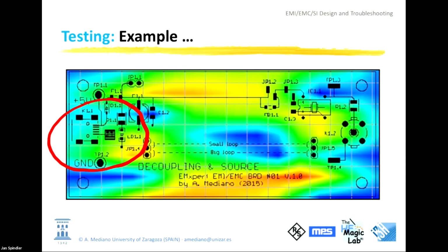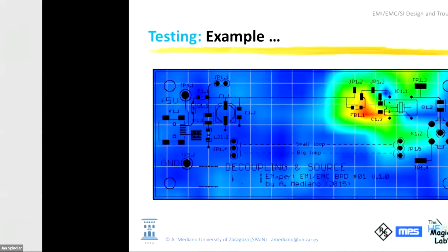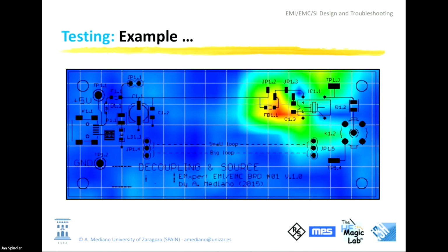The important thing is, when you introduce the decoupling system, what happens? How do you think that this will change with the decoupling circuit? Where will the energy be? Instead of around the PCB, creating crosstalk, creating radiation, creating common mode impedance in sensitive traces in this ground system, the energy will be around the element that is the source of the transients. So this is the result in the same scale. The energy is concentrated. You are controlling the energy, and this is very important for EMI.